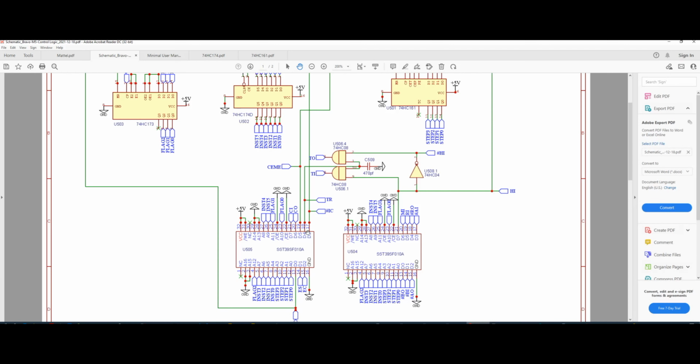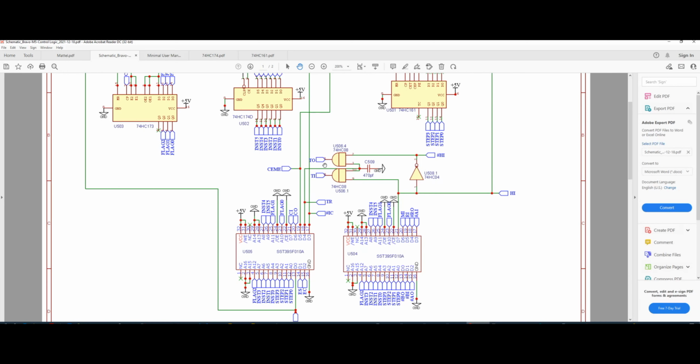So that means that for transmit and receive, what we're really outputting from the chips is a single TR and also an HI signal, which we combine to generate the TO or TI. The HI signal itself is coming from the chip on the right-hand side, which is the least significant byte chip, pin number D7.